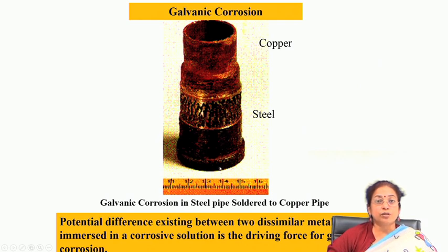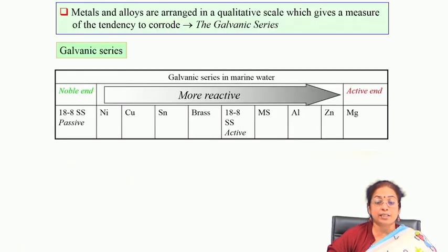So, galvanic corrosion can be a dangerous form of corrosion which starts at the interface and then proceeds to a large extent towards the other side of the component, and it is naturally a kind of localized corrosion. It occurs not only in dissimilar combinations, but also when a metal has dissimilar phases. Depending on the corrosion probability or EMF of the individual phases, there may be micro galvanic cell formation, as a result of which galvanic corrosion proceeds.